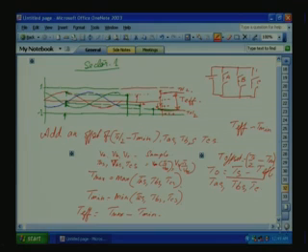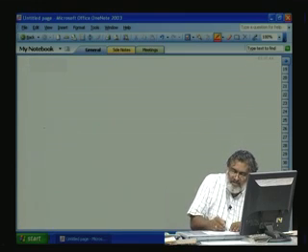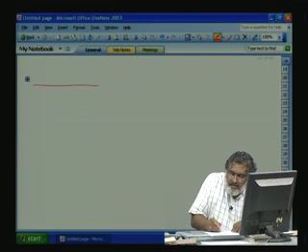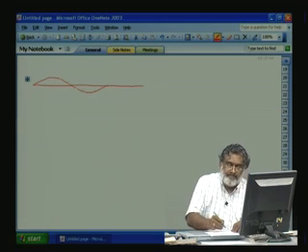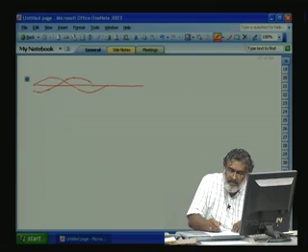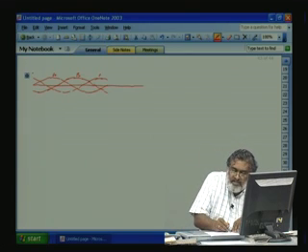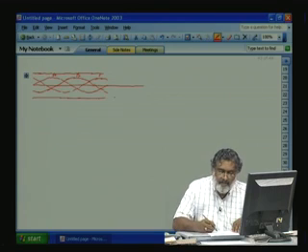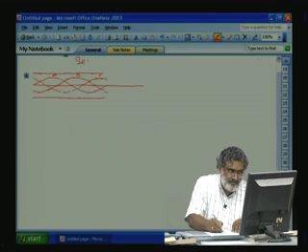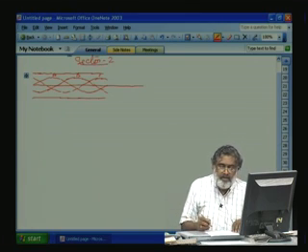So, let us go to sector 2 now, and see how it works. Let us find out the sampling instant for the T0 by 2 period. So, this is our 0 line, this is our A phase, this is our B phase, this is our C phase, that is A, B, C. Now, we are sampling. This is our maximum positive limit for the Vs with the maximum radius inscribed in the hexagon, or the maximum modulation index. So, here for sector 2, we are sampling at this point.